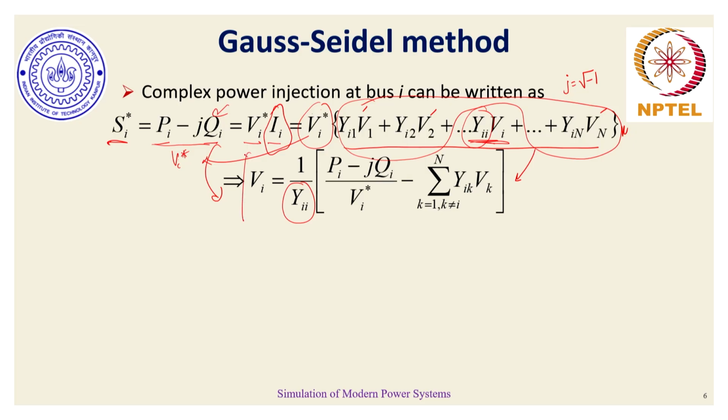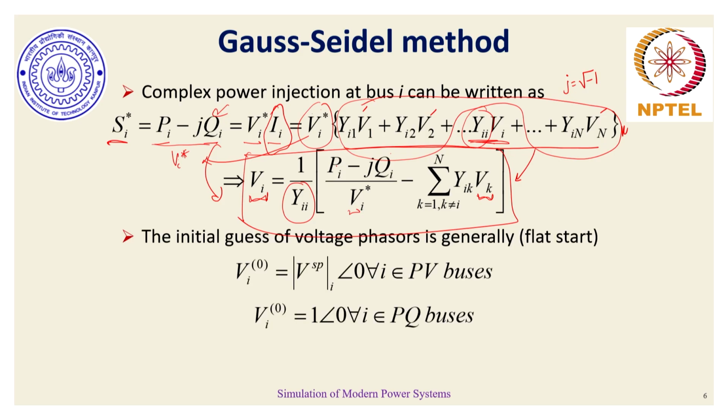And now, with this as my closed form voltage form, where P_i and Q_i are mostly known for PQ buses, we will find a way also of knowing P_i and Q_i for the PV bus also. We are getting an unknown V_i in terms of the remaining other unknowns here. So, that is where the Gauss-Seidel method now becomes applicable. So, let us see how we do it.